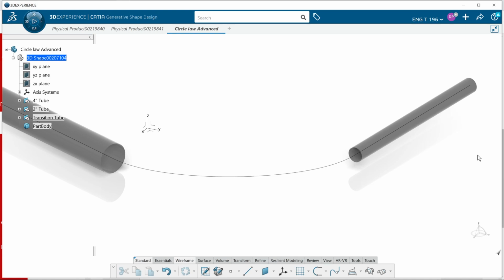In the tubing commands, you have special smarts you can have to know when you have hydraulic runs or tubing, if the tube is fitting into a male or female part, whether or not they truly are compatible and stuff. So when you create your logical lines, if you have this line going this way and this one's going this way and this one's going this way, they're not all going in the same direction, you could potentially create a headache for yourself. I only know that because many times that's bitten me when it should have worked. You can't see anything wrong. You're positive you're doing all the steps right.